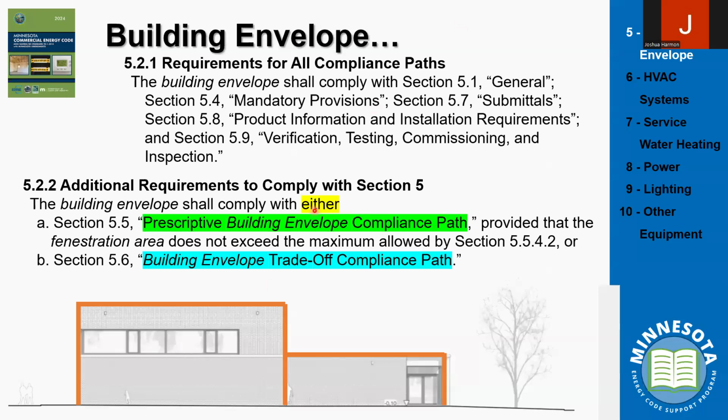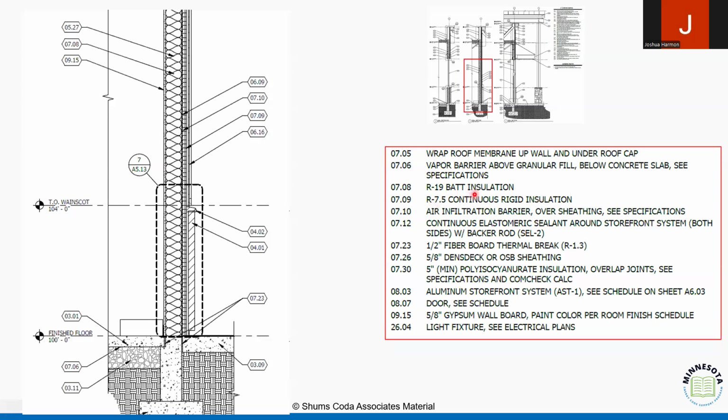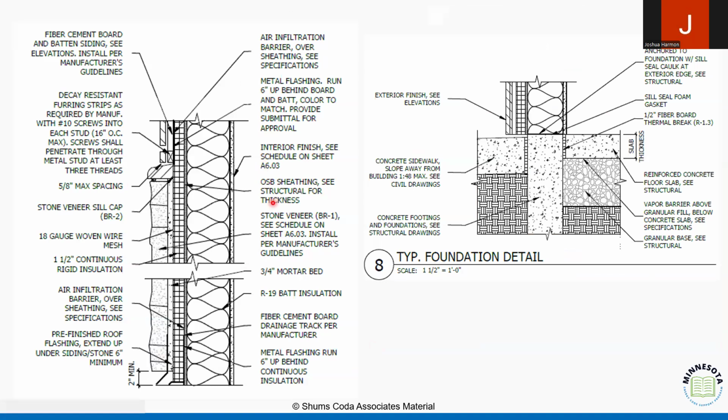Now, like I said, when we start putting in those values, all we're doing is putting in one place all of our mechanical and lighting values. That's just a tool, just another way to give us quick access to the values, right? But what we're really using COMcheck for is this process of verifying: does the wall match what's in COMcheck, right? Let's see where we got our insulation. And I think this is another example where we don't have those values identified.